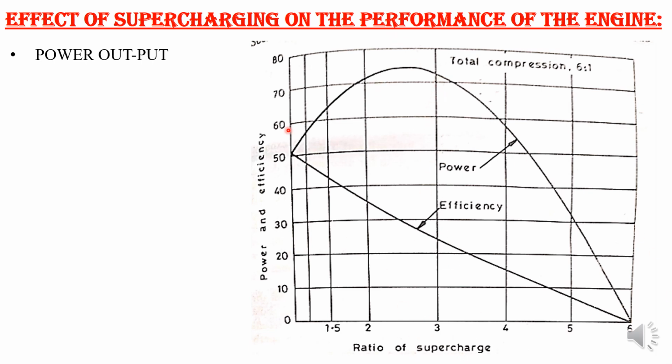But in contrast to that, as the ratio of supercharge increases, the efficiency keeps on decreasing. So we have to fix it with respect to how much extra power you want, at the cost of efficiency, and that you have to take care of. Okay, why does the efficiency decrease?